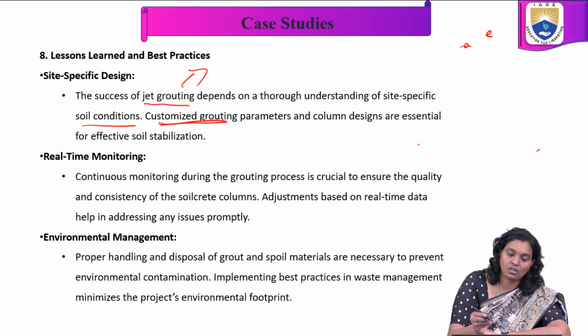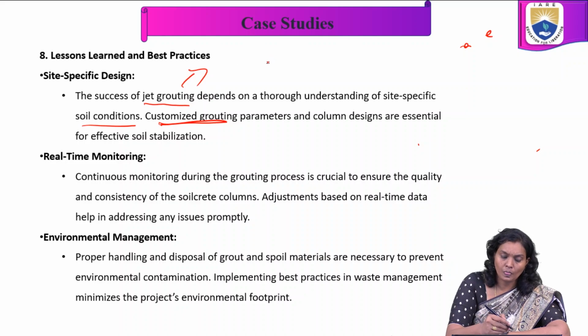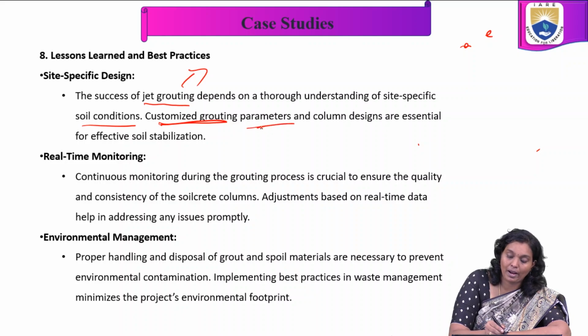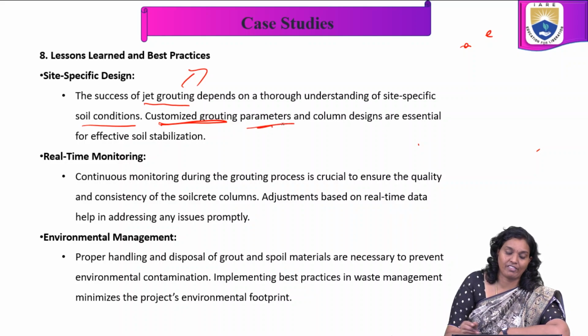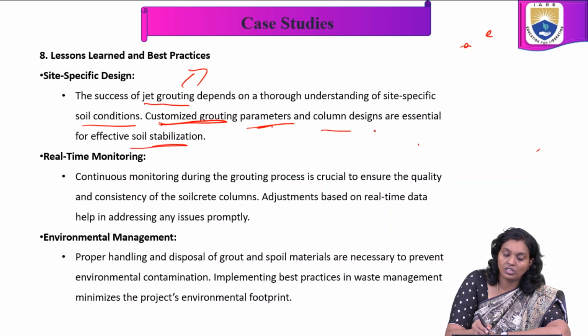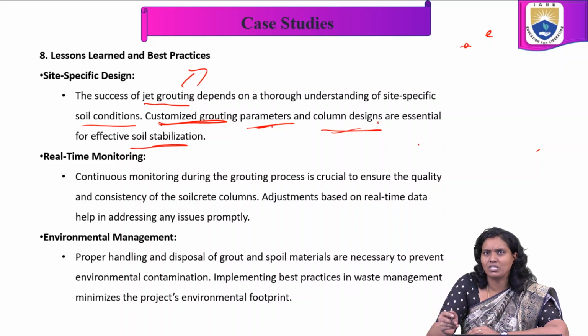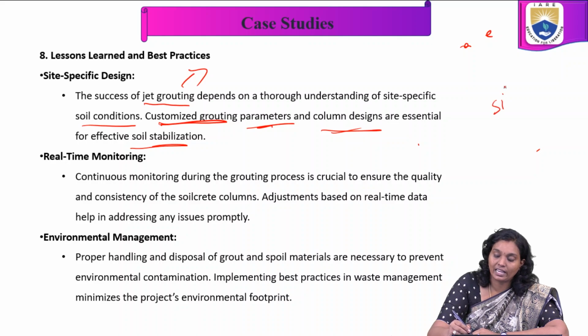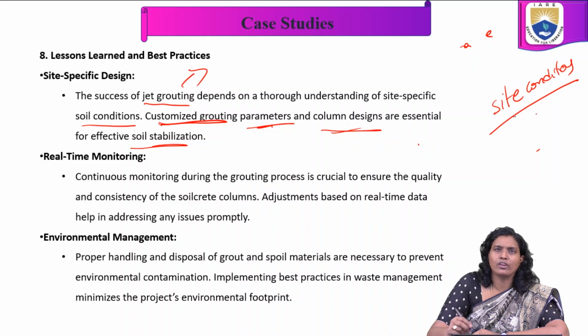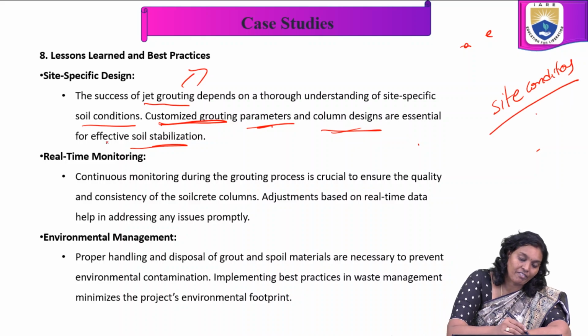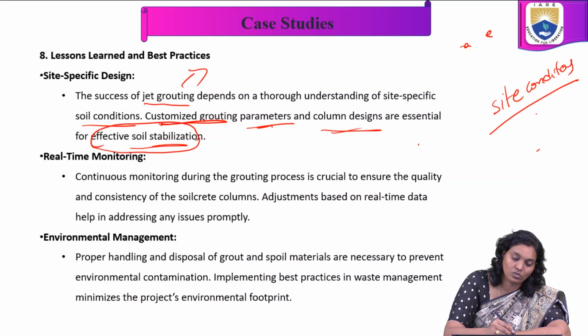In these customized groutings, various materials are involved, mix design proportions are involved, and all the various parameters are involved. The customized grouting parameters and column designs are essential for effective stabilization. Here also the column design, the diameter and how much depth, depend on the site conditions. According to that we are going to choose. So that gives effective soil stabilization, and gives the desired or required properties.